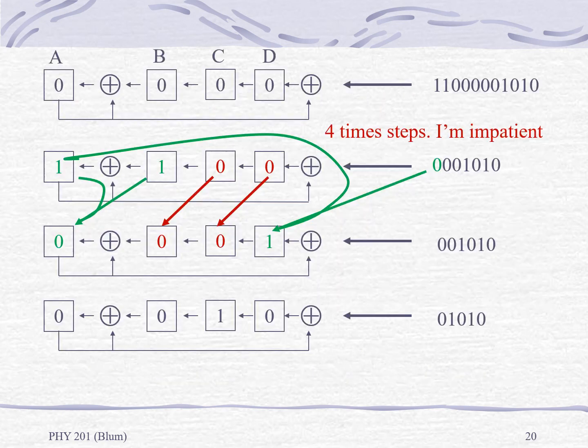Now what we're looking at here is a very simple CRC. I've got a 4-bit shift register. I've labeled the positions A, B, C, D to be able to talk about them easily. And then I've inserted 2 exclusive ORs, between A and B, and then between D and the new data that's coming in. The second input to those exclusive ORs is the bit that is in position A in the previous step and getting ready to be shifted out.